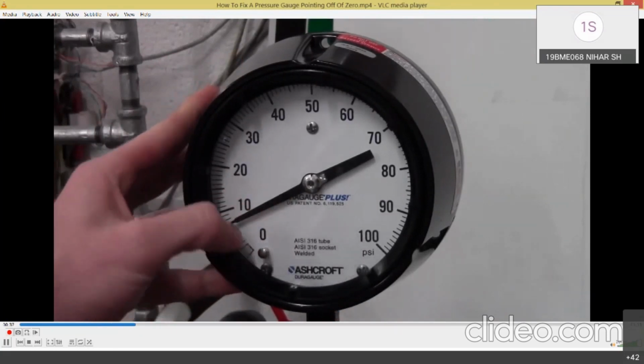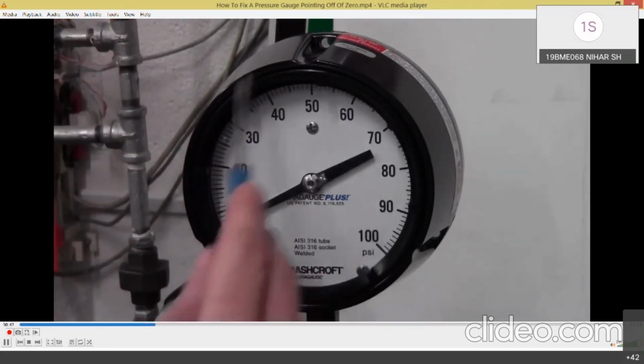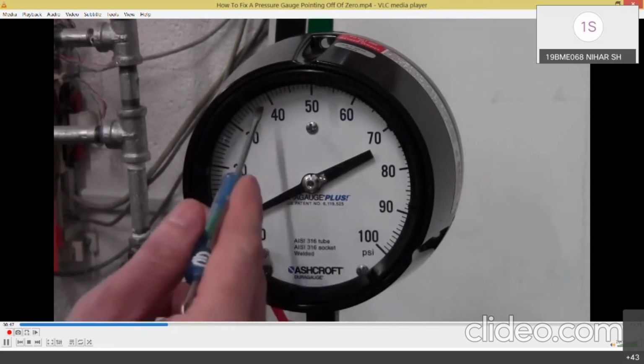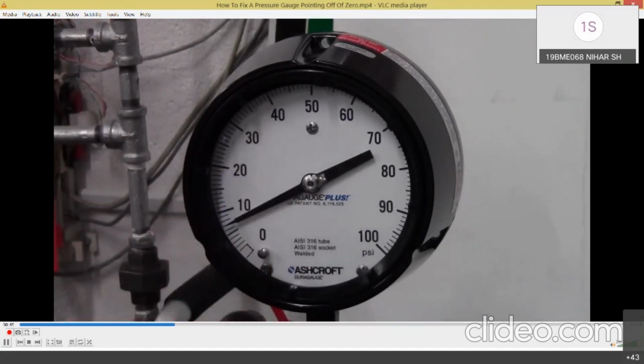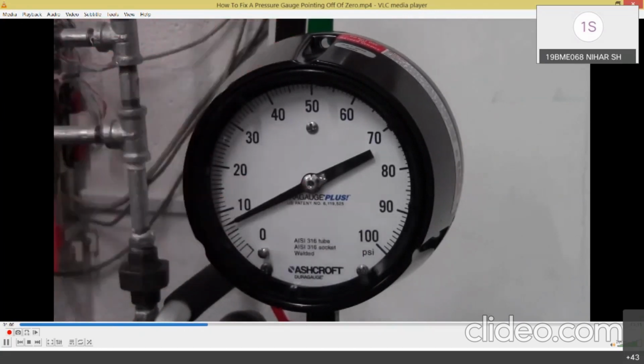Now, as long as your gauge is roughly off by between 1 to 10% of the nominal range, so within the 100 psi, this is obviously around 8, you should be able to adjust it. If your pointer is pointed at 40 at 0, it needs to be fixed another way. The adjustable pointer is utilized just to kind of fix roughly around 5 to 10% when it's off a little bit. So what we're going to do is we need to get access to the inside of the gauge in order to move this pointer.